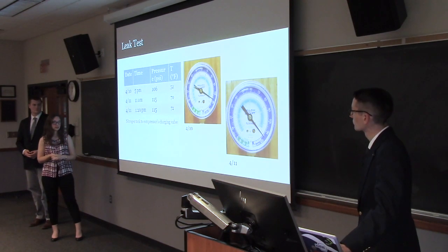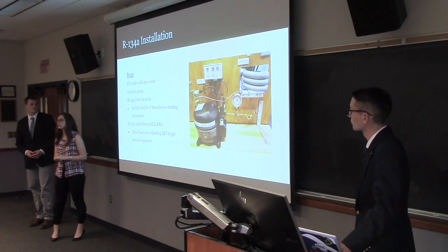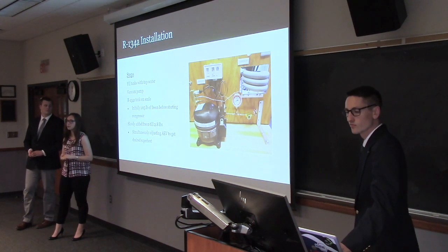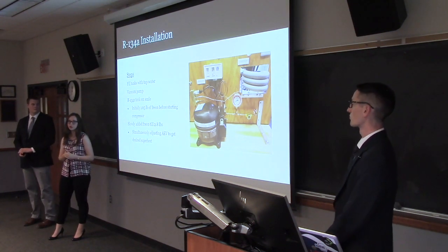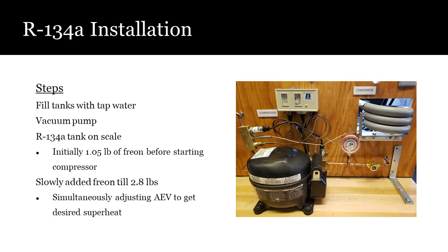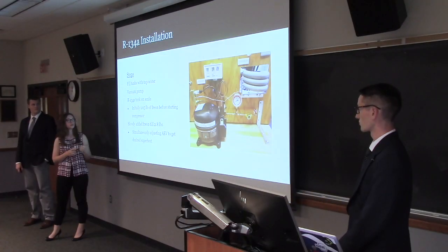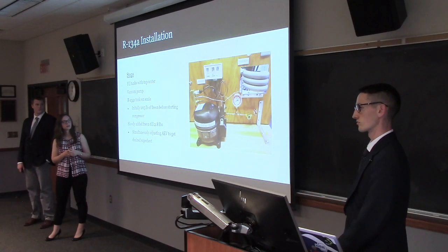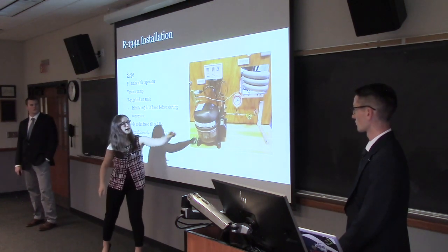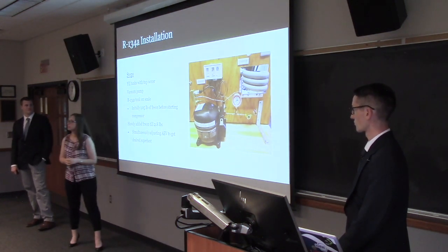So we got in contact with Sean Barnes, Grove City College's Director of Maintenance, and he sent one of his guys over with a couple pounds of Freon to help us install the refrigerant. What he did is first he used a vacuum pump to empty the system, and then installed the R134A tank to the same charging valve on the compressor that the nitrogen tank was hooked up to.